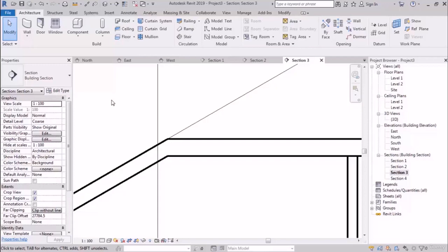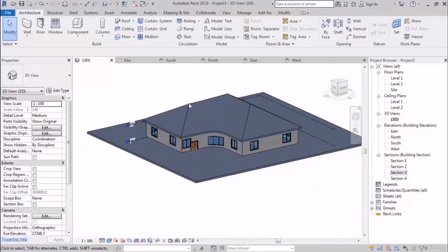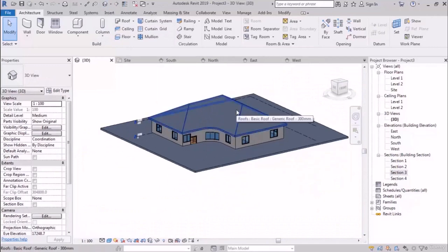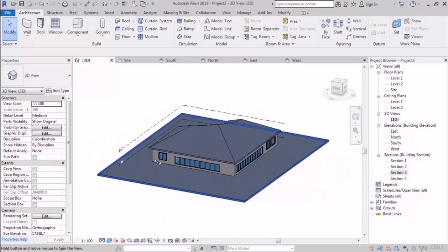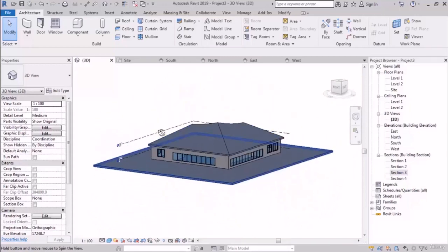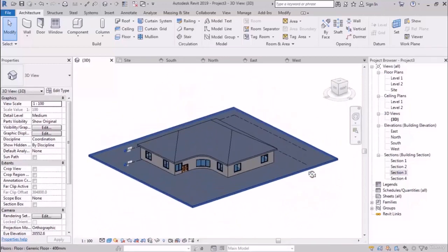But how can we turn around our object in the 3D view? Well, we can navigate that. If you want to turn around your object, just hold the shift and then click on scroll. In this way you can turn around your project. But there's a point here. It's better that while you are turning around your project, you choose an object as the center of your turning.